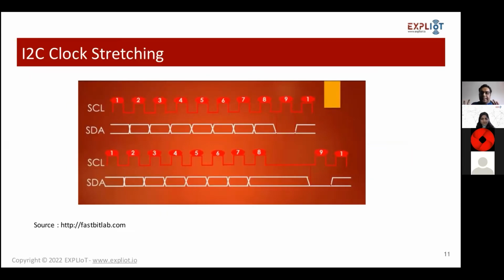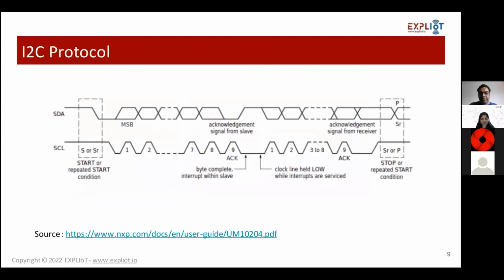Now, the next thing in I2C is about the stretching of the clock. This is one of the challenges that happens in I2C communication. What happens over there? Let me go back to the scenario where we have this I2C communication, where the data has been sent and acknowledgement is there, which is perfectly fine. But if you go to the basics, the serial clock from the master is controlling that communication. Now, there may be the possibility that the slave, who is in synchronization with this clock, may not be able to follow this clock thoroughly. And there is a challenge for that.